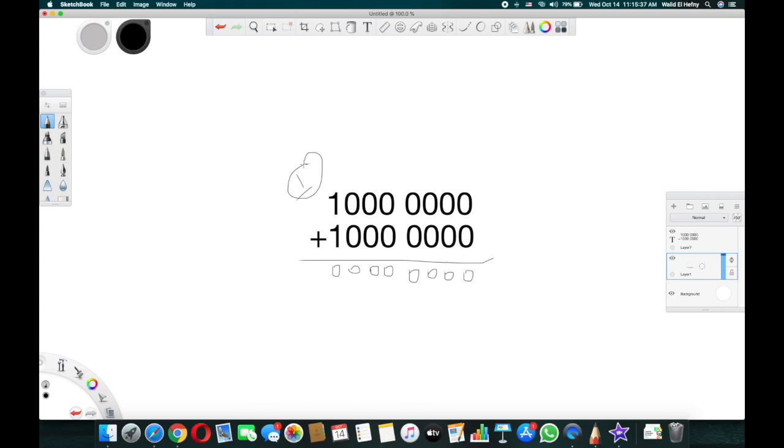Okay, I repeat it because it is very important. Having 1 at the end means we have a carry, and carry is actually important to unsigned numbers. To signed numbers, we do not care about the carry. However, our microcontroller is not smart enough to actually know whether we are performing a signed or an unsigned operation. It is just performing calculations on bits. Therefore, it is the role of the programmer to know what type of operation they are performing, a signed or an unsigned operation. However, both the overflow flag and the carry flag, which we'll talk about later, will be updated after every arithmetic operation, regardless whether it is signed or unsigned.